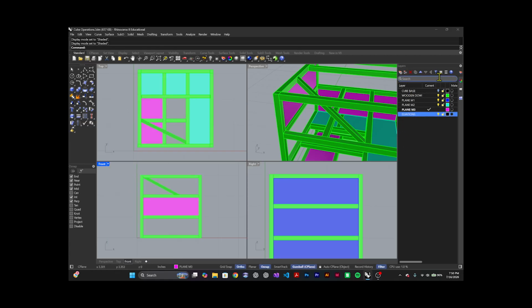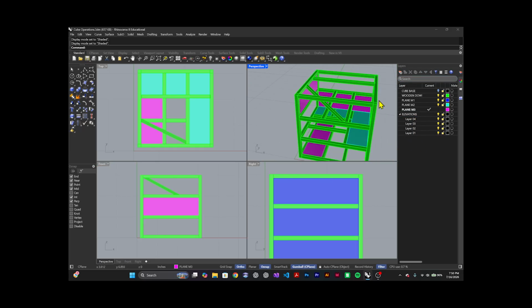So elevations. Now again, I'm gonna redo this just so you guys know how to do it. We're gonna click right here, new layer. I'm gonna rename it elevation or elevations. Then I'm gonna click that layer and then click right here. I want sub layer. So I want one, two, three, and four just in case. Why? Remember, we have four layers of information, one, two, three, and four.